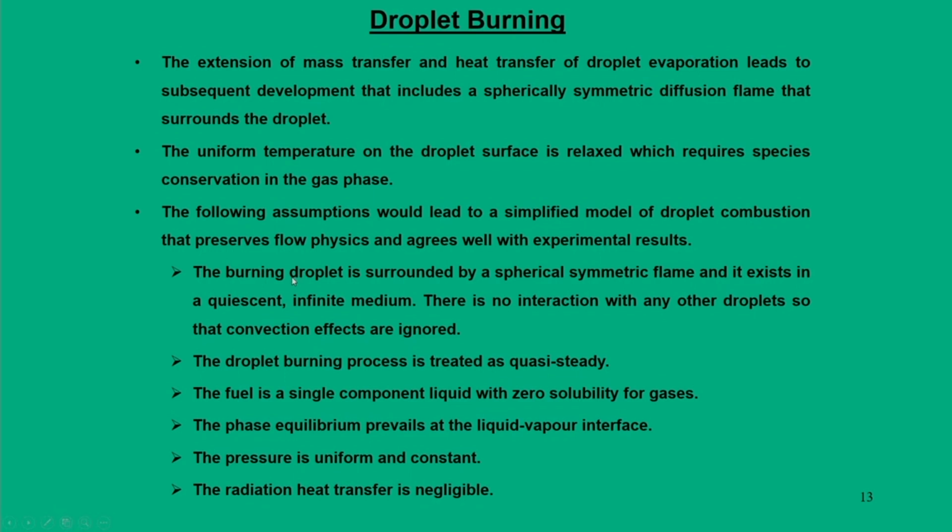However, there are certain assumptions that have to be considered to frame these governing equations and find their solutions. The burning assumptions are as follows. The burning droplet is surrounded by a spherically symmetric flame and it exists in a quiescent infinite medium, and there is no interaction with any other droplets, so that convection effects can be ignored. The droplet burning process is treated as quasi-steady. The fuel is a single component liquid with zero solubility for gases. Phase equilibrium prevails at the liquid-vapor interface. Pressure is uniform and constant. Radiation heat transfer is negligible.